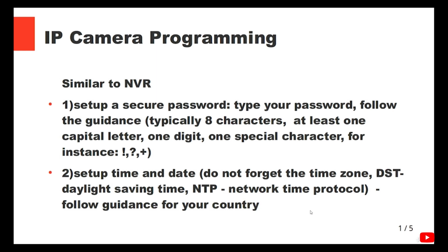Because for many IP cameras, if you leave it alone, the camera will stay in the time zone from the producer, which for a lot of them will be China, and a lot of IP cameras display their own time on the NVR screen. So then you have weird situations where the main time of the NVR is, I don't know, 5 o'clock, and the camera is 8 hours off.